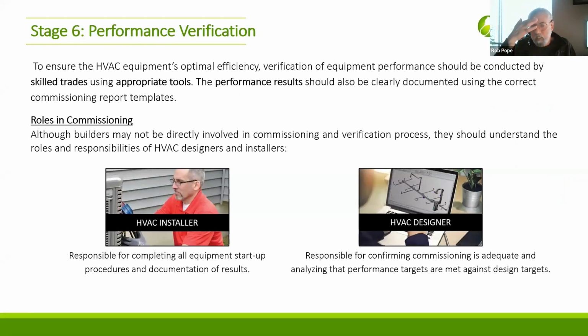Performance verification at the end, I can't state enough how important it is. It is so critical. The equipment leaves the factory, has no idea where on the planet it's going to live. It's just default settings. You have to configure it, set it up, and test it. And you want to do the shakedown anyways before the homeowner moves in to see if there's any component failures that are warranty related, for example, right? Or you missed something, but now you can fix it. You want to get it working, checked out, everything sorted out before the homeowner comes in.